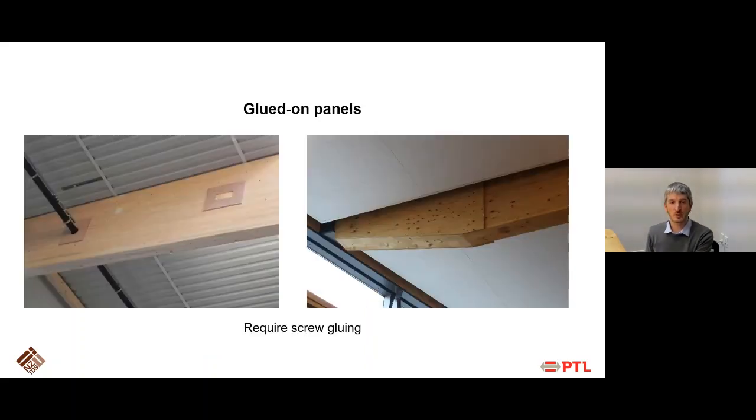We can also use glued-on panels. Typically, they're glued-on plywood panels. They require screw gluing to apply the pressure, and the guideline actually provides you some information on how to obtain this screw gluing.